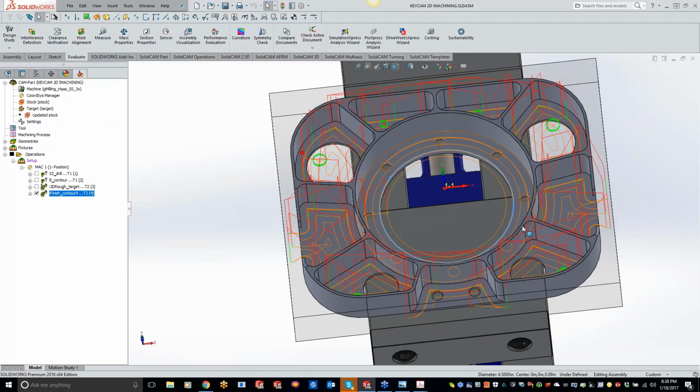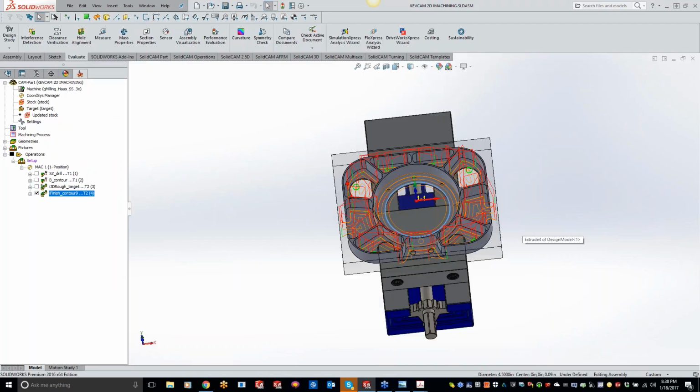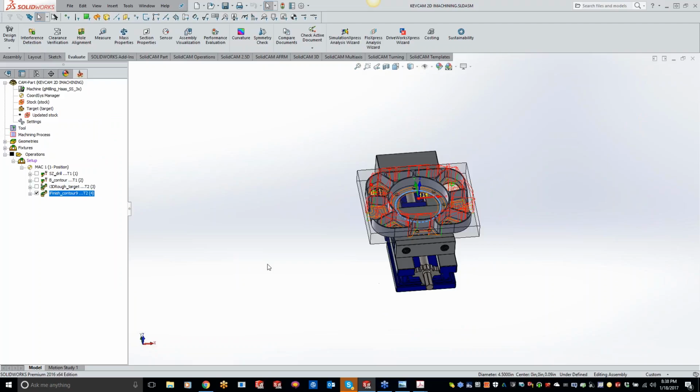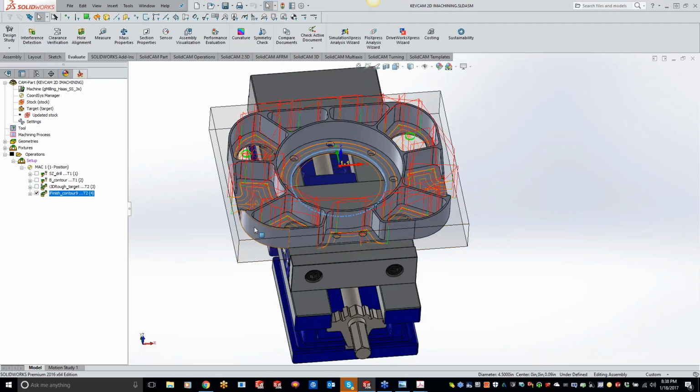Okay. And same thing for the outside. You'll notice that I didn't do iMachining on the outside doing the finish pass in there, but exactly the same thing is what we did before. You just click on your stock right here and mark that chain as open.